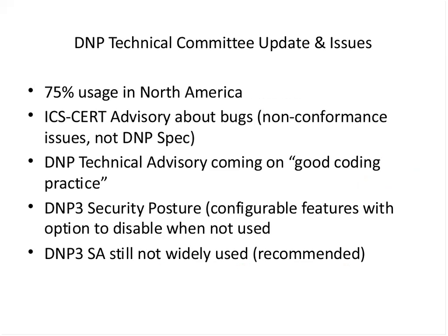And what we need to do is find ways in which the various protocols that are supported in transmission and distribution, like C37.118, 61850, SIM, and DNP, how they're all going to coexist. What are going to be the appropriate interfaces for the data exchanges? What services are supported where? And do they support the business function? Because the final arbiter is the business function. That decides whether your protocol is working for you or not. If it doesn't have the services, then you're in trouble.